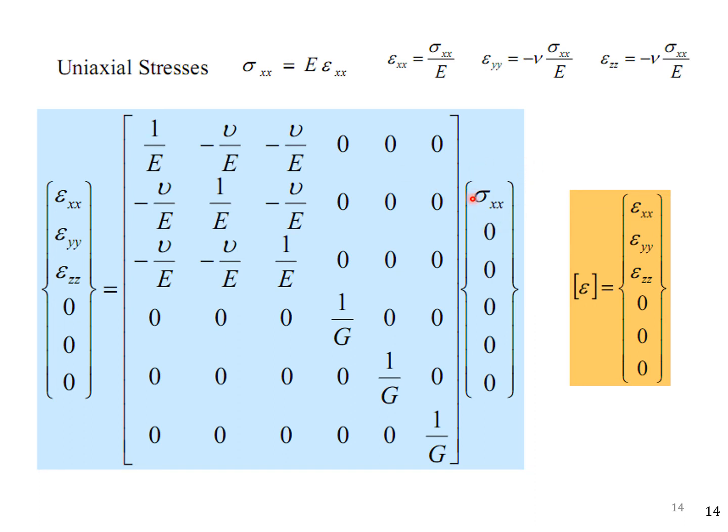So if stress is applied only in one direction, meaning unit axial stress, we have talked about it, it will have three components of strain. So the components of this constant, we will have 36 components, and they can be calculated using this stress and strain relation.